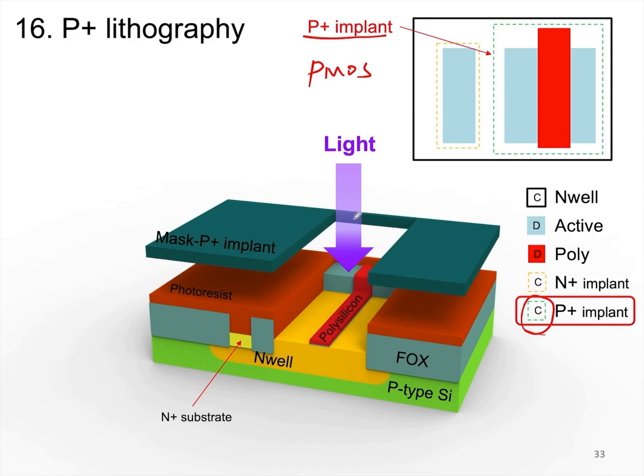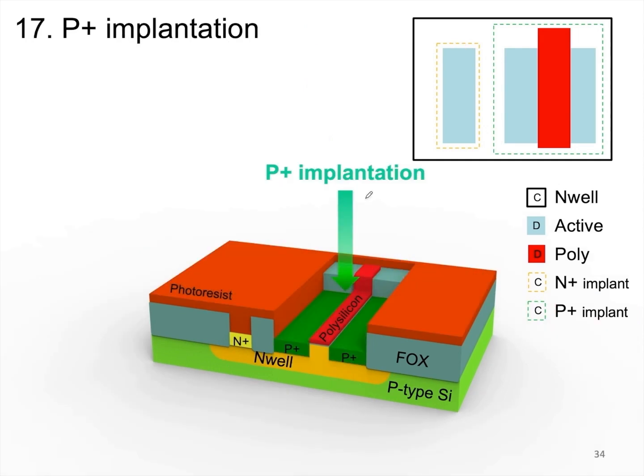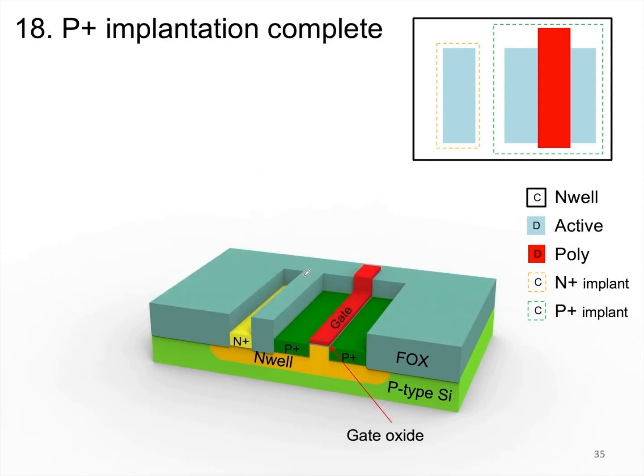For our photoresist layer, the areas with patterns are hollow, while the areas without patterns are covered. So only the areas with patterns can have the photoresist etched away, right? After etching, we perform ion implantation, and only the areas where the photoresist has been etched away can receive the ions, while the remaining areas cannot. Alright, at this point, our P-type implantation is complete. The source, drain region, substrate, and polysilicon have all been formed, right?